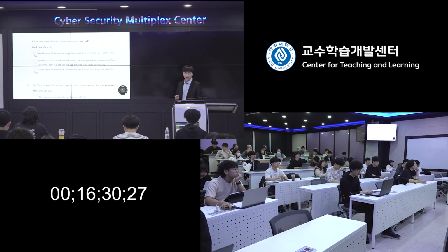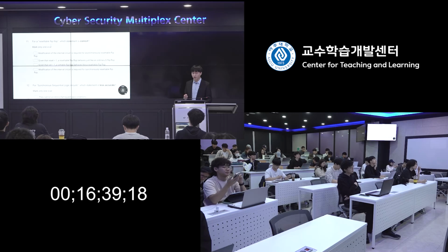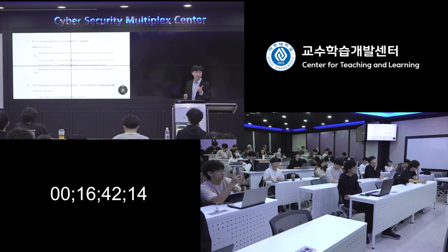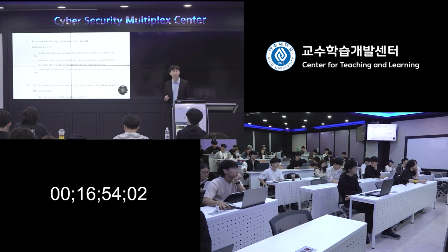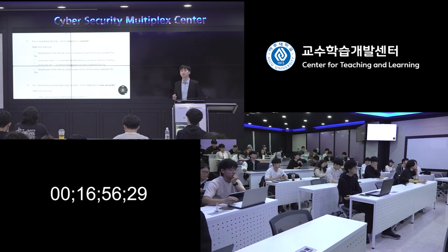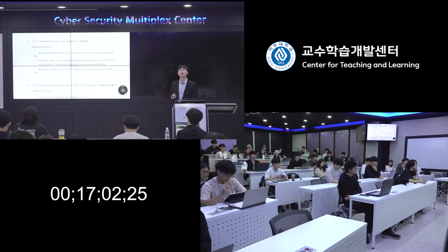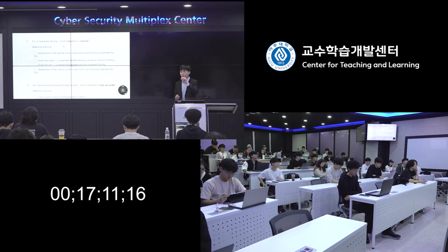I don't know why, but if you read through, the correct answer is actually obvious. So firstly, it's a resetable flip-flop, right? What is a resetable flip-flop? When you put the reset equals 1, what happens? Anyone? Force the Q to 0. Sorry? Force the Q to become 0. Yes. So it's like reset, right? If you put reset equals 1, it forcibly makes the output Q be 0.